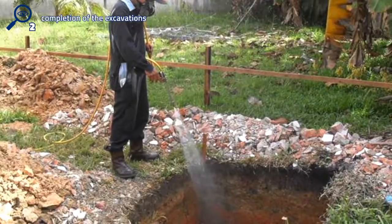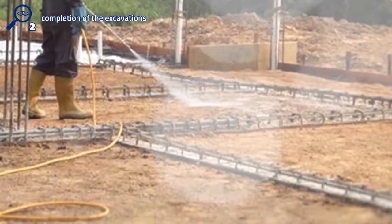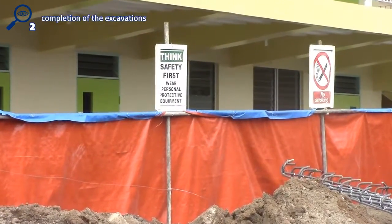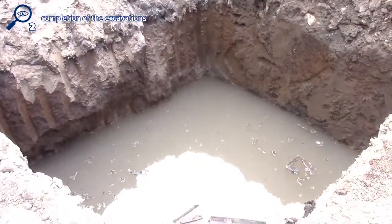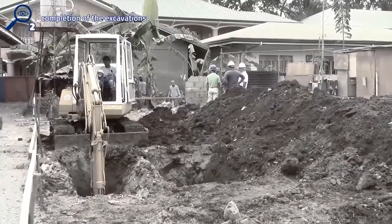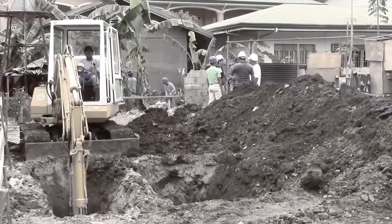That the testing for soil poisoning has been carried out and that the results are satisfactory. That safety barriers are provided in all excavation areas. If the engineer notes during the inspection that the excavations are creating unstable ground conditions, the engineer must report this immediately to the school division superintendent and if necessary, issue a work stoppage notice or temporary suspension of works until issues have been completely addressed and resolved.